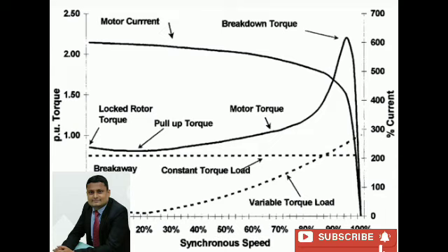Corresponding to the operating flux density in the stator core, BCS, that was chosen earlier, iron loss per kg of the material can be found out from the graph. So multiply this specific loss value with the total weight of the stator core, which gives the core loss in the stator. So now another loss will be friction and windage loss.